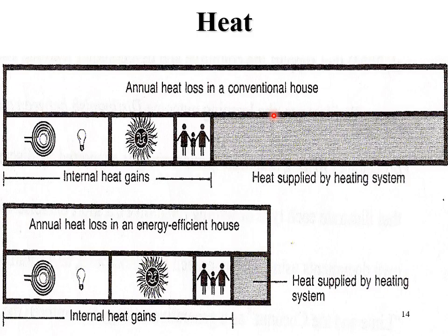But then if the cost of all this heating would double, that would be a lot more in terms of your yearly costs. So a lot of times when you do home comparisons, you compare energy bills and see what the energy bills are, and then you can also rate them for the future. And so a lot of times the insulation will pay for itself, and that's excluding the advantage of insulation of making the house more comfortable, quieter, cleaner, all those things.